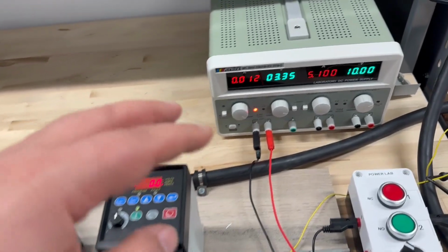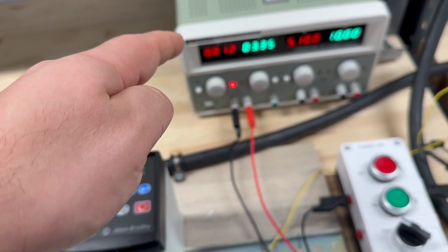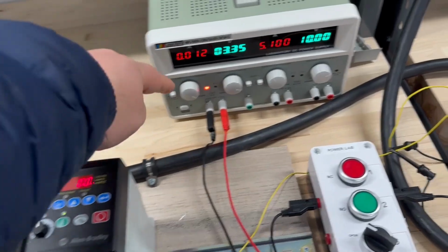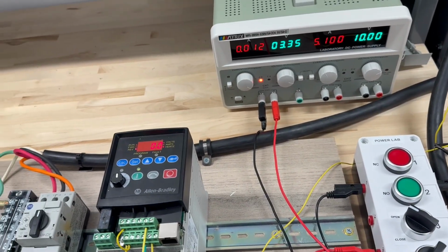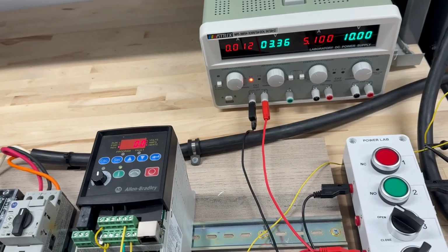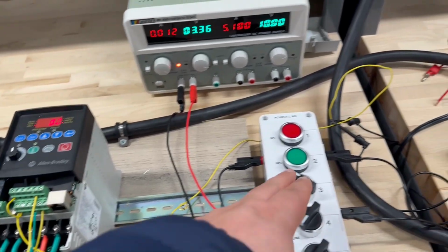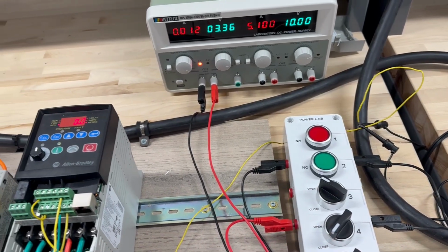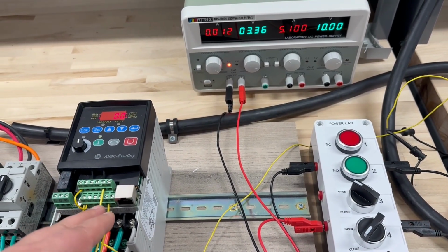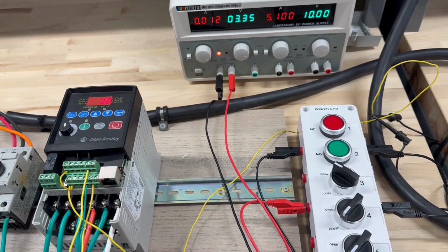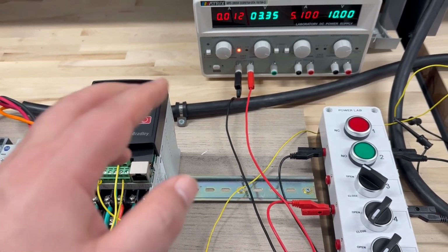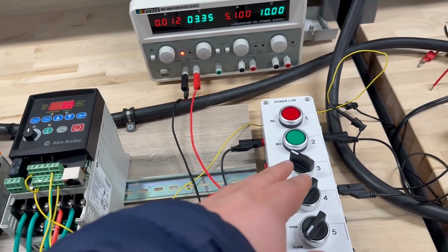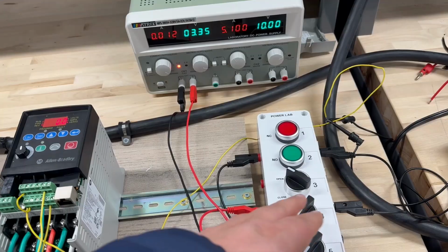Just for the wiring, make sure we are using this as a current source right now, and I am able to adjust the current with this knob that I have here. For the second thing, I have a small switch. I connect one side of this switch to the 24 volt, and the other side to terminal 5. You will see in a few minutes why we did that. So that means just ports 14 and 15 go to the current source, and terminal 5 connects to the switch, which has one side at 24 volt.